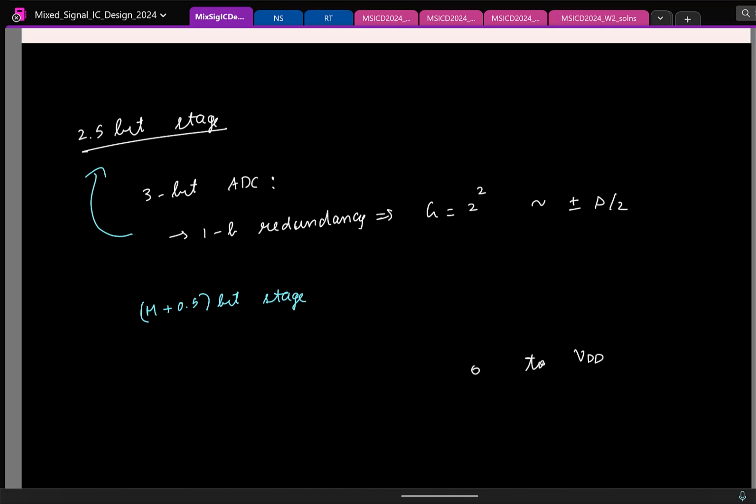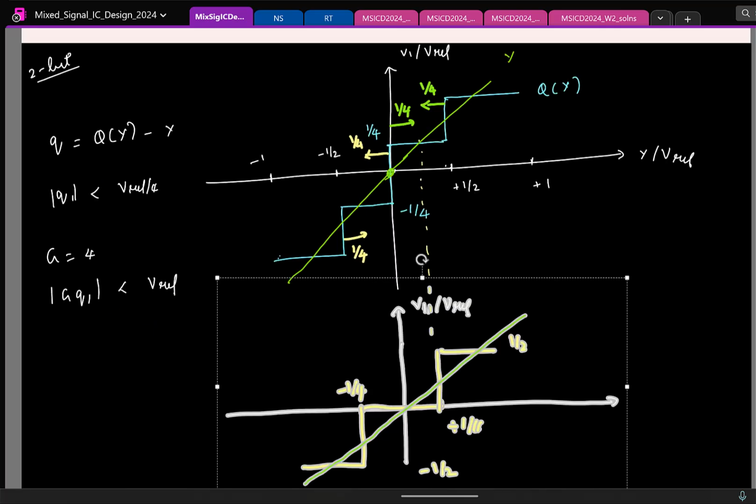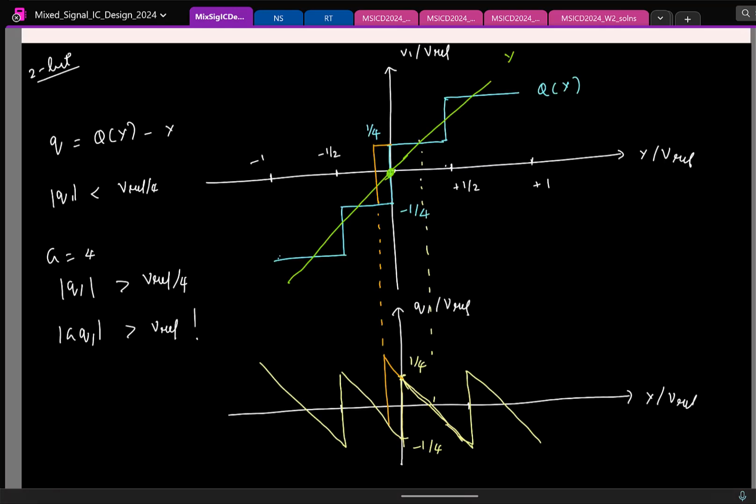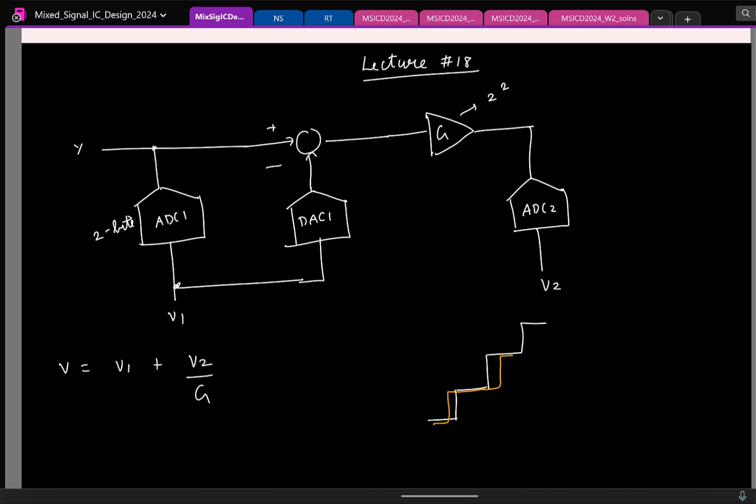So this is how we tackle any issues in the ADC. Now we know that if you make an error in the ADC, how you can tackle it. The solution is to use a smaller gain here, so that even if you make an error, you are fine.